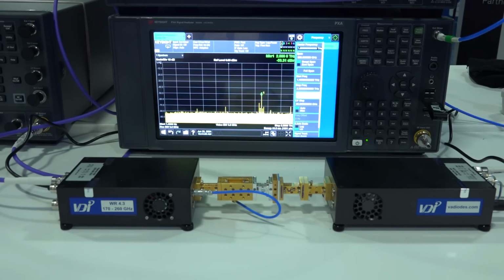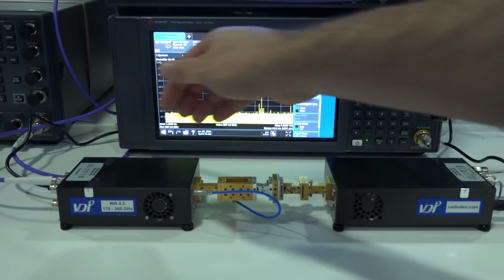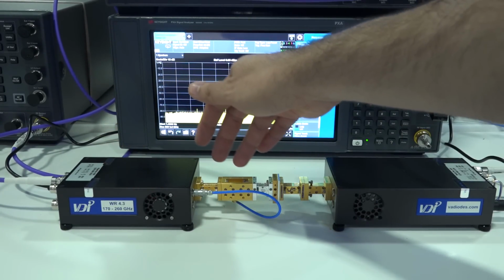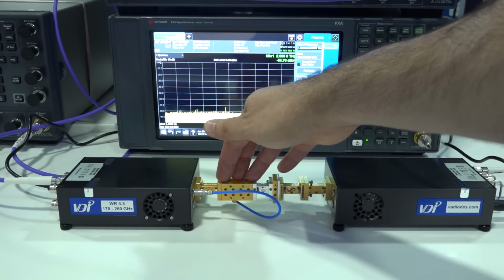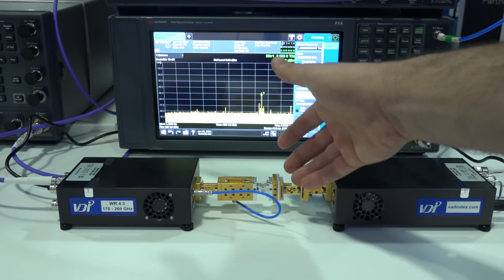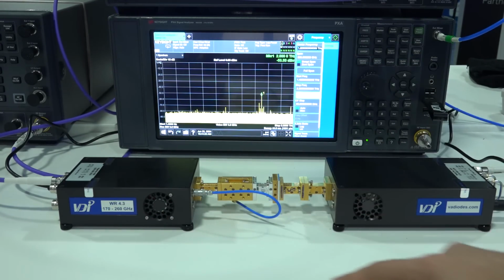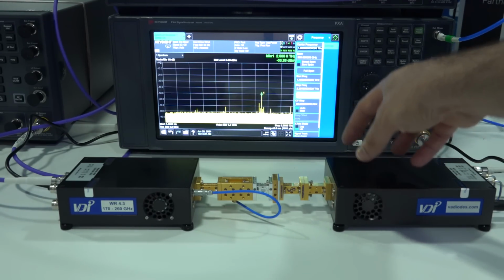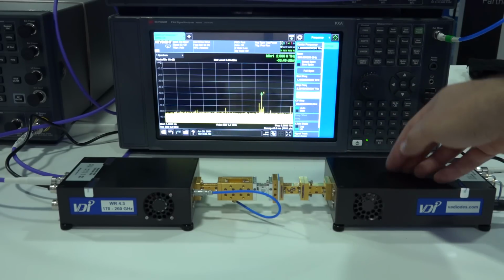And here we're seeing a little bit of an insight on how VDI plans to get to frequencies above 1 terahertz. So this is actually a 2 terahertz setup, which itself is quite crazy. So we have a 170 to 260 gigahertz multiplier front end that goes into a power amplifier, also indium phosphide, and then that gets multiplied by 3 and then multiplied by 3 again. So you have a factor of 9 multiplication, which of course will take you over to 2 terahertz. And then over here we do have the prototype version of a 2 terahertz down converter. So now you have a complete 2 terahertz system.